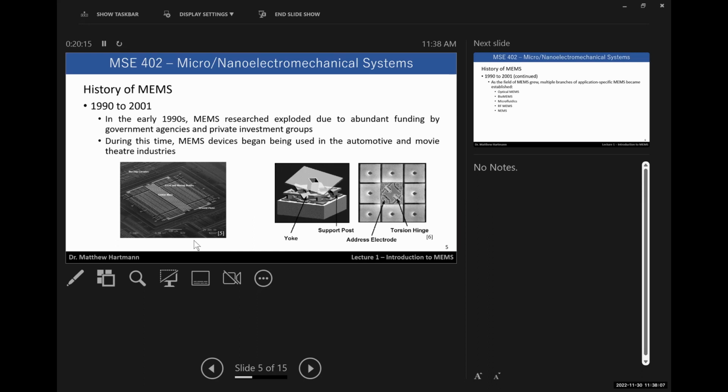If the memory cell contains a 0 or digital 0, the micro mirror is deflected 12 degrees in the other direction, effectively scattering light. So each one of these mirrors is a pixel. They're tens of microns in dimension, so you can put millions and millions of mirrors in a very, very small chip, and that's how you get high resolution for your movie projectors and all that kind of good stuff.